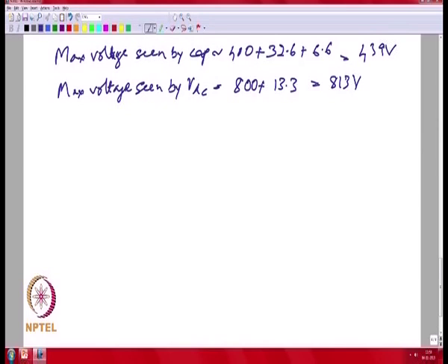So, the ripple voltage above your nominal voltage is about 2% ripple overall, which might seem reasonable. It is a tight design, but it is actually doable. So, you might have to be cautious about your control design, so that you do not have large overshoots on the DC bus capacitor. So, you have to precharge it slowly etc.